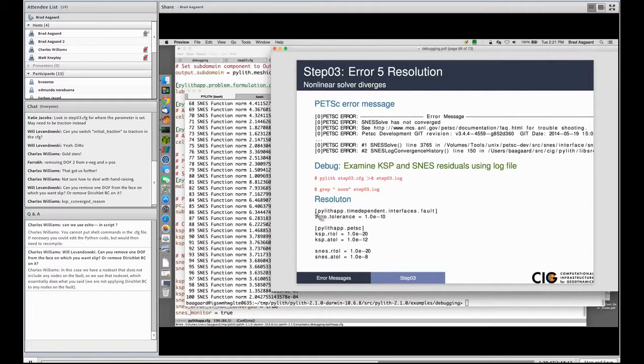We're going to add this zero tolerance, and then we want to force our slip to be smaller than that tolerance. So that means that we really can't rely on the relative convergence tolerances and the KSP and SNES tolerances. We really need to force them to be an absolute convergence.